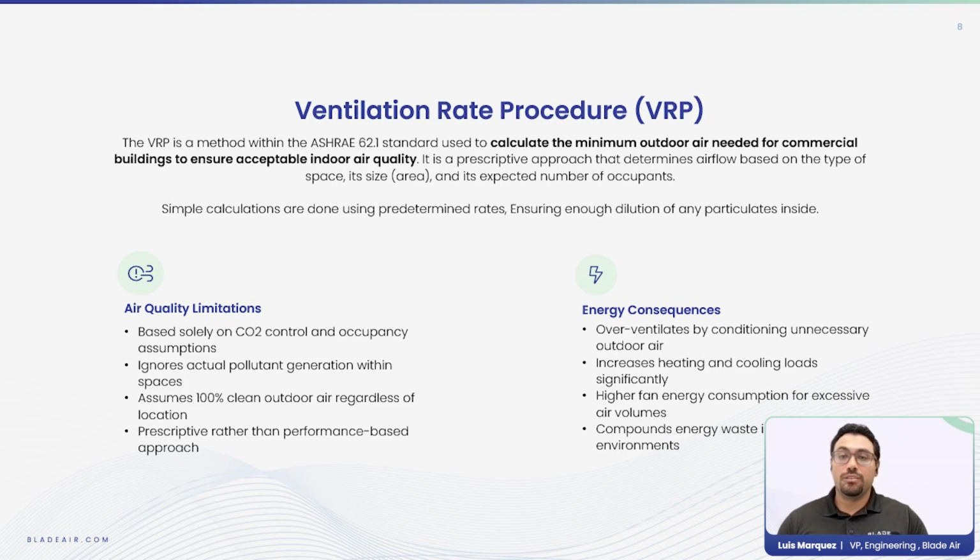And so what that leads to is that it requires you to condition many times large volumes, regardless of whether that conditioning is actually necessary for air quality. This can become particularly problematic in urban or industrial environments where outdoor air may actually introduce more contaminants than it removes. It can also bring potentially harmful gases and particulates to indoor settings during events like wildfires.